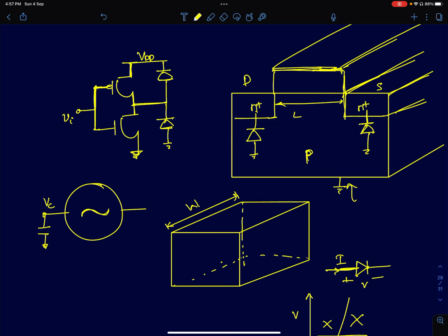The problem the engineers were dealing with at that time was how to keep the voltage across the capacitor constant. Because it's a CMOS IC, somewhere you will end up having some diodes. Either you put a switch, or there is some device connecting to that node that will end up having a parasitic, unwanted diode, naturally formed.